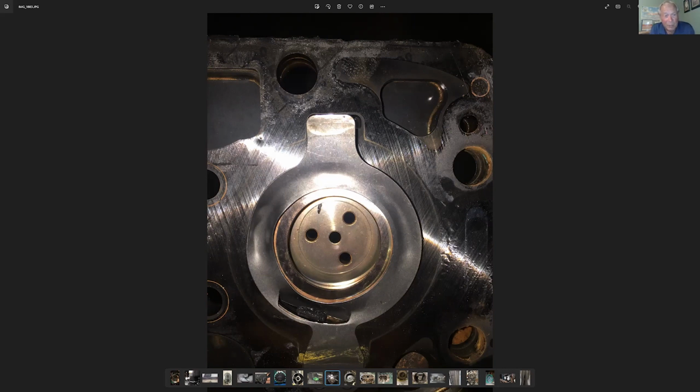But if the system wasn't designed with a crankcase heater, the technician may in the field decide that, especially when he's changed a compressor like that. And that's one of those extras when the OEM orders the compressor. Sometimes you won't see that in the supermarket world per se, but in some applications, they'll leave that off thinking it's not a big deal. You're not running the air conditioning in colder ambient temperature. It happens.